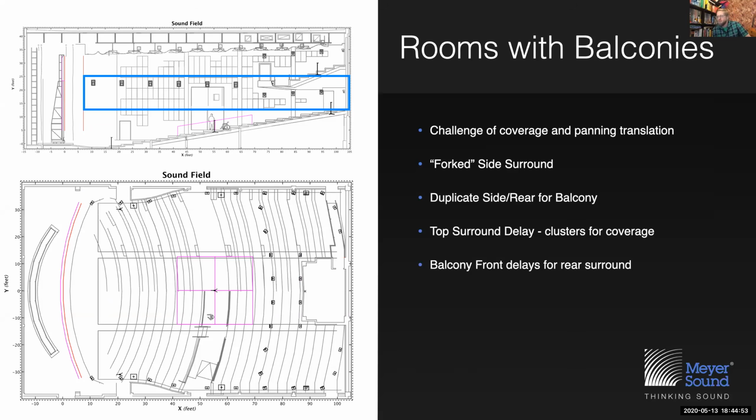What I wanted to specifically point out about that is if this were a 5.1 or a 7.1 system, those speakers would all be playing the same channel, and traditionally they might get one output from a processor because you might treat that as an array of speakers and only need one EQ for that.